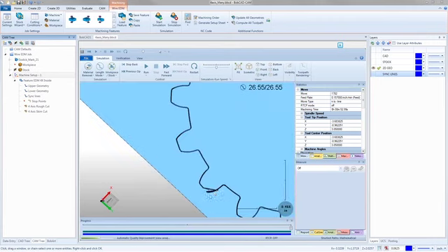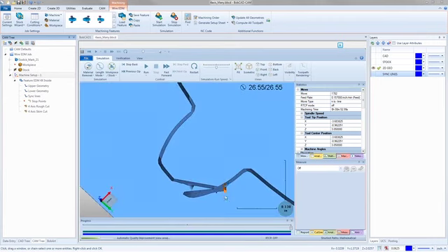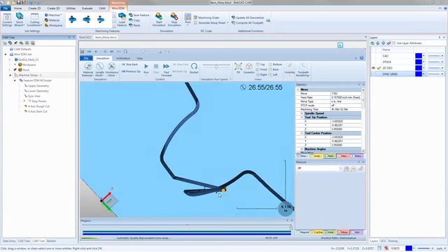There's probably a small connection. There it is. Some weird cut that happened down on the bottom. So we definitely have to go figure out why this didn't sync up nicely here. But that's the reason I'm unable to get it to break apart. It's because somewhere in here this isn't cut fully and it's touching. So it thinks when I say remove chips, keep one part or select chips, it's all one because it's touching. So we'll have to look at the start point on this and see what we've got going on.